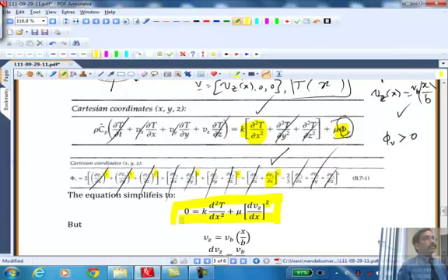Now, what is the difference between this problem and the previous problem where we had electrical heating? The source was constant, here it's a function. Exactly, the source was constant in the previous case. It's uniform everywhere in space. Here, the velocity gradient turns out to be constant. Why is it constant? Because the velocity profile is linear. When you take the gradient, it turns out to be constant.